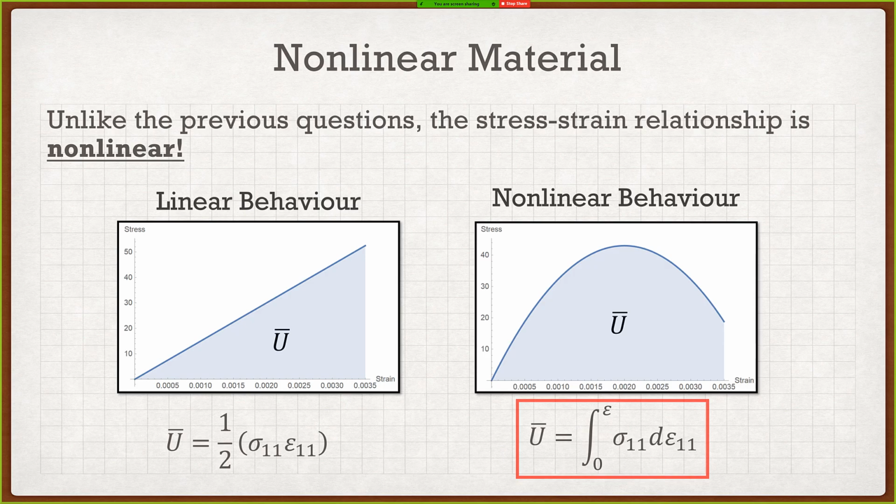You're on the right track. And the answer is when something breaks, the energy is released. It's not stored anymore. It's released in the terms of sound or the actual permanent strain, stuff like that. So you're right. When the concrete crushes, the energy is released. If we don't fail the material, it's still under all that stress. Therefore, it's storing the strain energy.